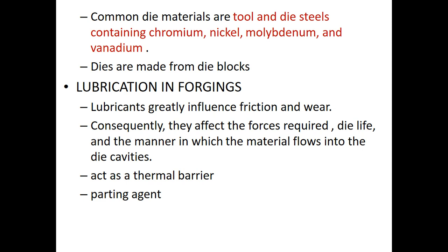This is added to increase the high temperature strength of the die material. And the nickel composition varies from 1 to 5 percentage. It is added to impart toughness and impact strength. Then vanadium varies from 0.1 to 0.3 percentage. It contributes to improved wear resistance and fatigue. And tungsten varies from 2 to 3 percentage to enhance the effect of other elements.